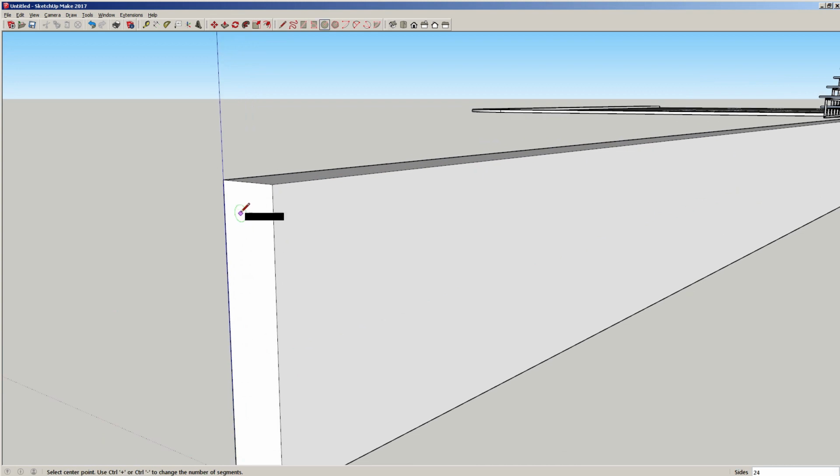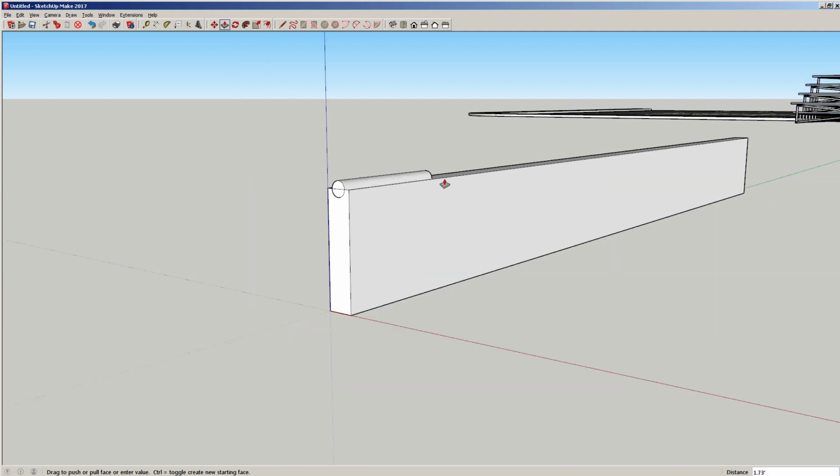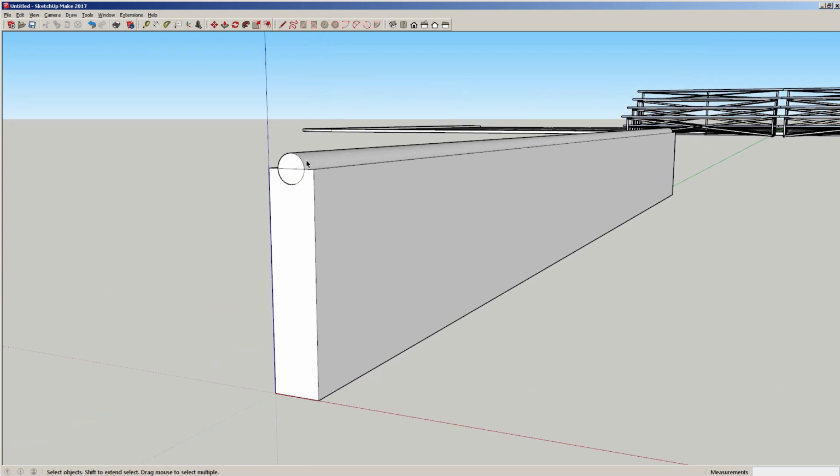So for here, press C. This is our circle. And we're going to start in the midpoint. For a decent sized rail, let's try 0.1. We're trying to mimic the size of pipe, kind of like making coping, which we've done in other lessons. Press P, and remember to click and release. Now that it follows your mouse, let's snap it to the end of this rectangle. Alright, pretty simple. Now triple click that, right click, make a group.